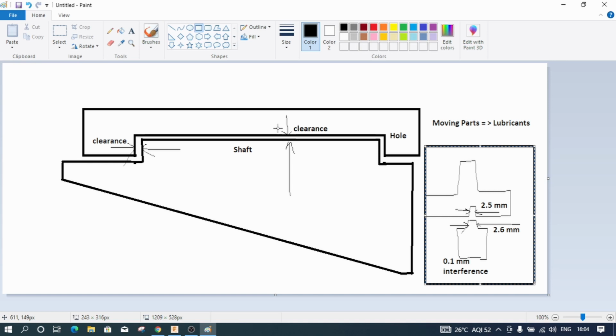You need to engineer, you need to master these particular interference fits and clearance fits, and you should also know what the manufacturing tolerances are. Those are actually dealt with by very large scale molding industries where their entire full-time job is exclusively dedicated to engineering metrology itself. But as we are starting out printing small models for our customers at very low cost, we will experiment with this, and as we increase our expertise, we will slowly enter the space of plastic injection molding, where we will be dealing with these kinds of interference fits and tolerance limits.